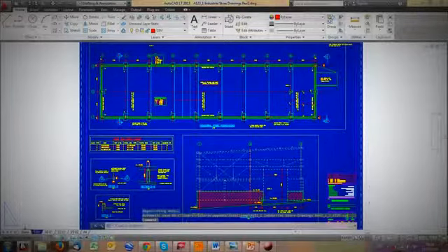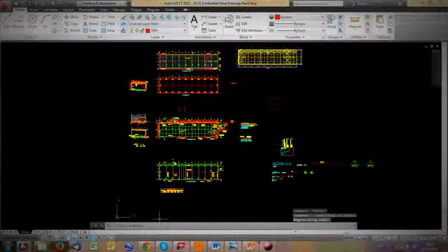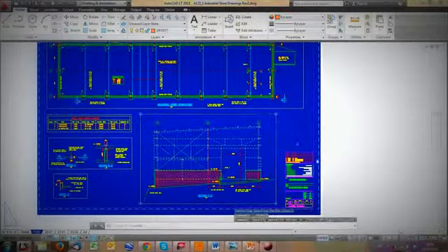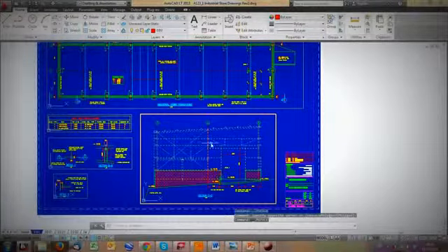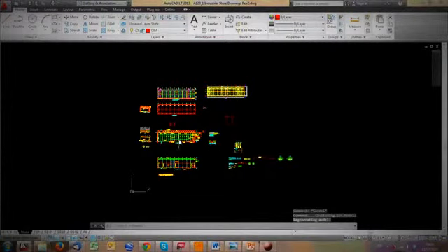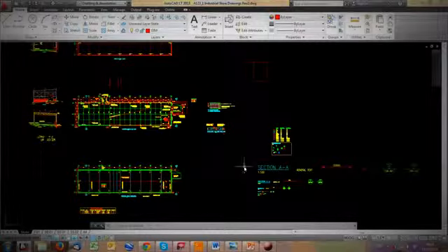Now, I just actually clicked on model, and it then moved me from model to Paperspace. If I clicked on paper, it'll open the Paperspace. So if I'm in my Paperspace, and I click on a window and I click paper, now I'm in model space again. All right, from model space, now we want to start having a look at the settings, for instance, for dimensions.